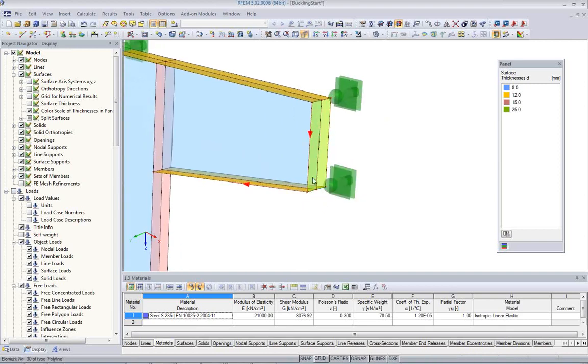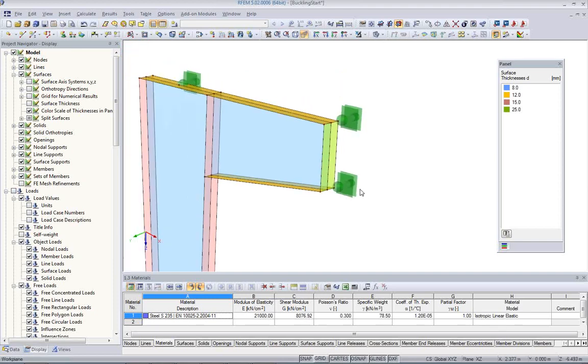Typically what you should not do is to introduce the load on one finite element point node. So it's better to distribute the load along the depth of the beam, and the length of this center line here is 600 millimeters, just remember this. If I want to introduce a bending moment of about 360 kilonewton meters in the center of the column, I need approximately, because we have here 2 meters, 180 kilonewton of force here at the end of the beam.